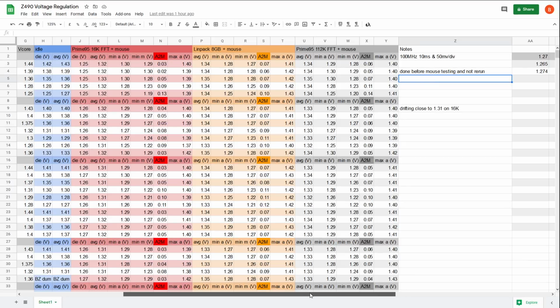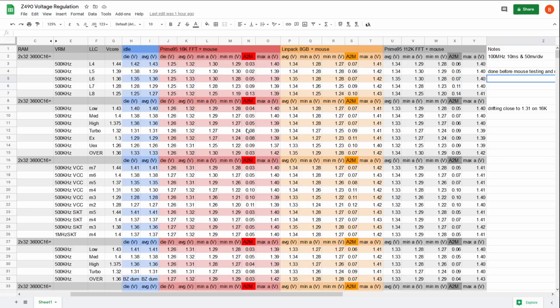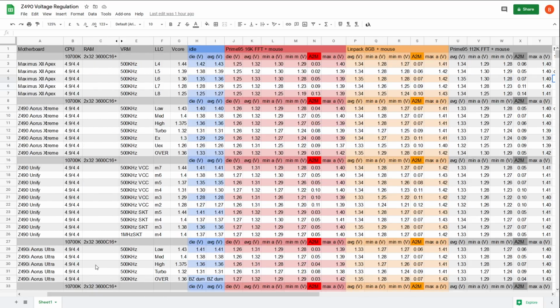And in terms of the probe that I'm using, I just had a bit of coax going all the way to the CPU. So we don't have to worry about a 10x probe; I'm not using one. This is all 1x with coax, and it's 50 ohm termination at the oscilloscope. Right before the oscilloscope, I have a 50 ohm termination because the Rigol doesn't have internal 50 ohm termination. If I got another new scope, I'd like one with internal 50 ohm termination. I'm not sure that would make a massive difference, but it could be better.